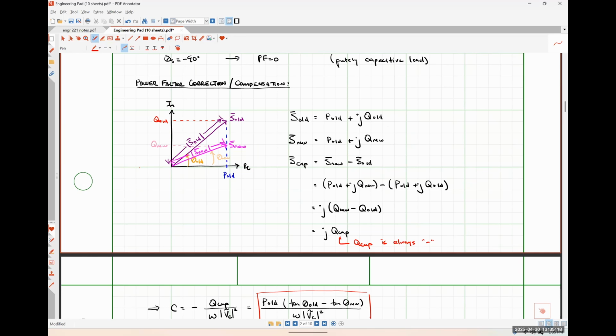So let's say you might add 2 Henrys of inductance for 60% of a half cycle, and that will correct some number of VARs. And if you did it for 80% of your half cycle, it would correct a higher number of needed VARs. So instead of switching in different inductors, it's always the same inductance, and you're just modulating the amount of time it's present in the system to get an average value for your power factor that's close to what you want it to be.